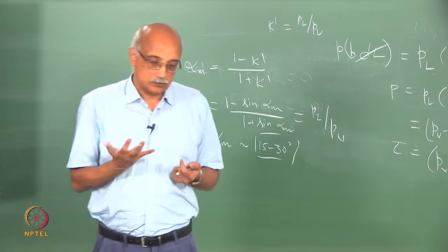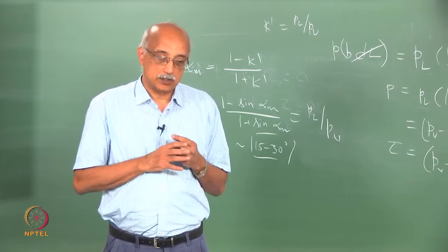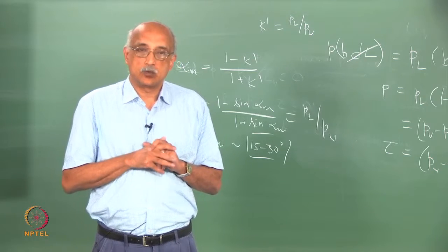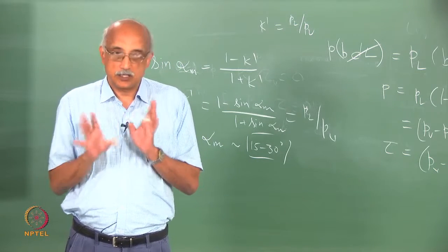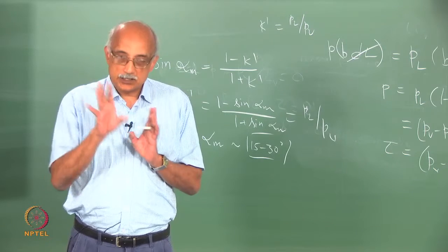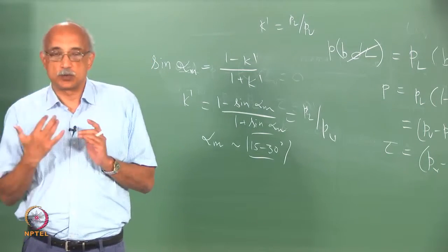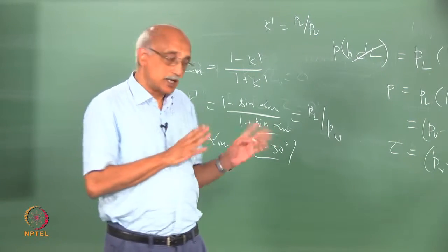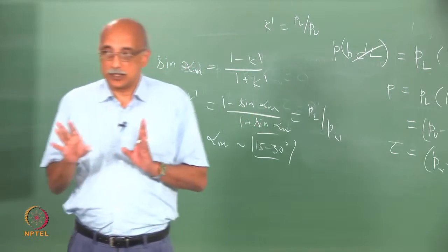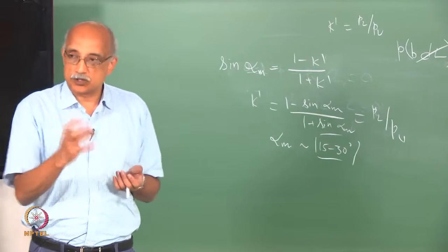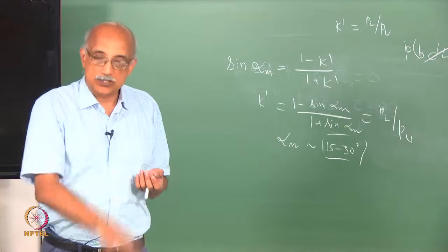When you get into fluid mechanics, there is a lot of discussion about compressible and incompressible flow, and one of the definitions of incompressible flow is that the density of flow must be non-varying along the streamline of flow. So, that is another principle that particulate masses violate, in the sense that, let us say that you open your silo and the particles start flowing down.